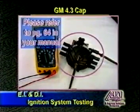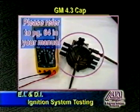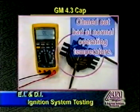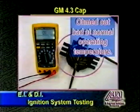There it is. Now, if you take the ohmmeter, this is a little bit tricky, so we will tell you that when we ohmed out that high voltage tower, the carbon button inside the distributor cap to the coil wire terminal, the ohmmeter, when the cap is still at operating temperature, ohmed out as an open circuit. So we know we got a bad cap.